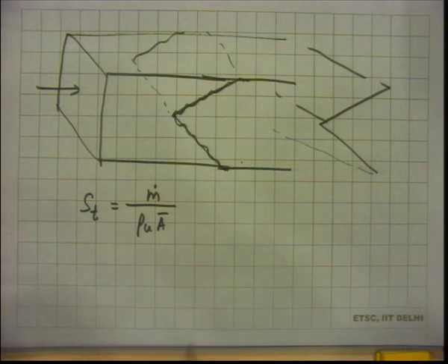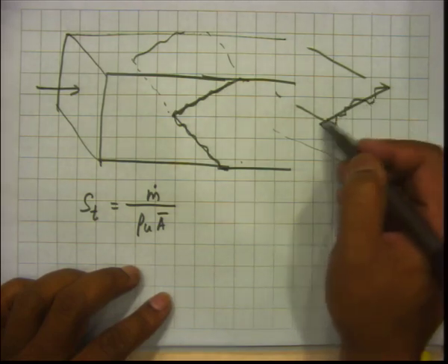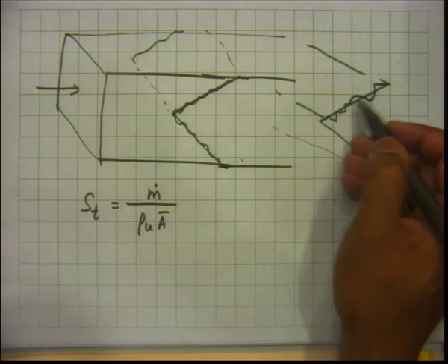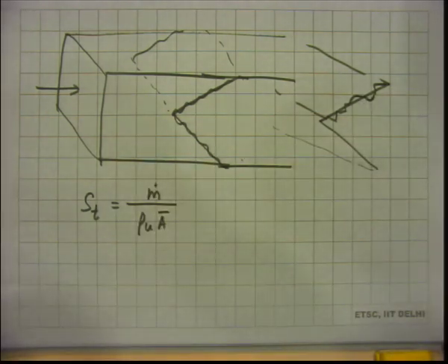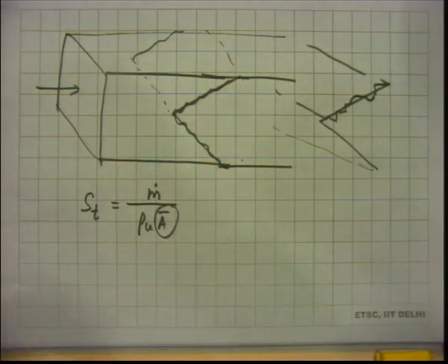So, that means the instantaneous area is the average area plus all these wrinkles added to it, right. So, this is a wrinkle, this is a wrinkle, this is a wrinkle, like that. All these added to the average area will give you the area of the flamelet. But we want to work with A bar. Okay. We want to work with A bar in the definition of turbulent burning velocity, right. You may say that A bar is not the area where combustion is taking place, but A bar is used in the definition of turbulent burning velocity.